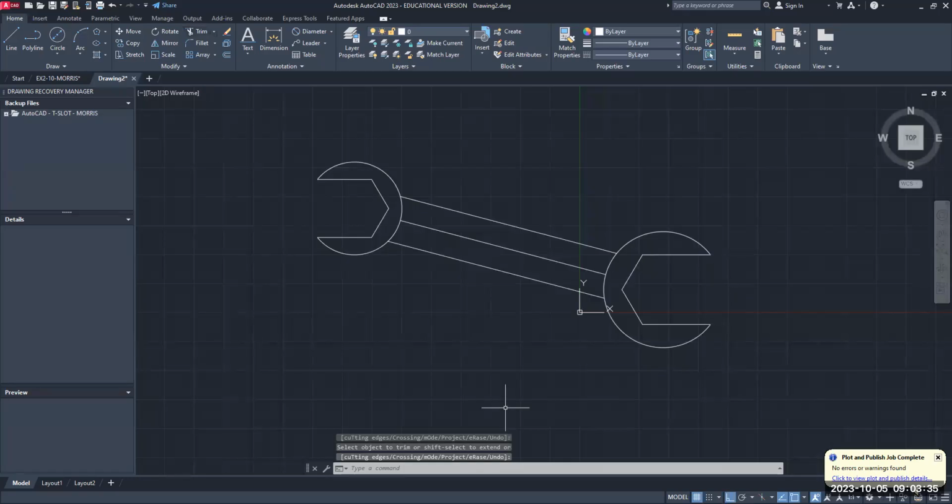It doesn't look anything like our wrench yet because we have to add the rounded corners, and they have a radius of 3. So up here, you can type in fillet, enter, and we're going to select this edge. Hang on, I forgot to, I'm sorry. Type in fillet. Mr. Morris gets AutoCAD and Inventor mixed up sometimes, forgive me.